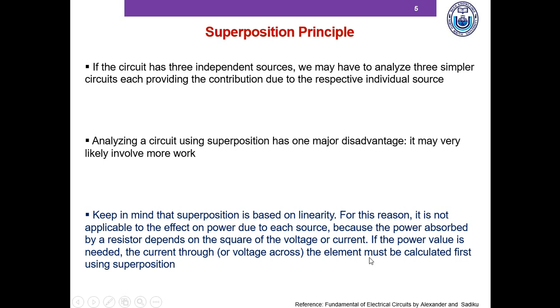Superposition is based on linearity, so we cannot use it to compute a variable that has a non-linear relationship with voltage and current. For instance, power. We know P is equal to I squared R, so power and current have a non-linear relationship. Similarly, power and voltage also have a non-linear relationship.